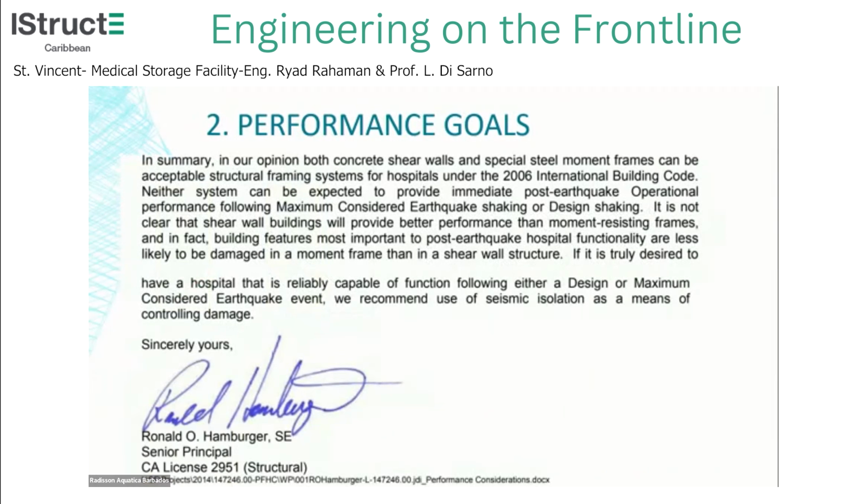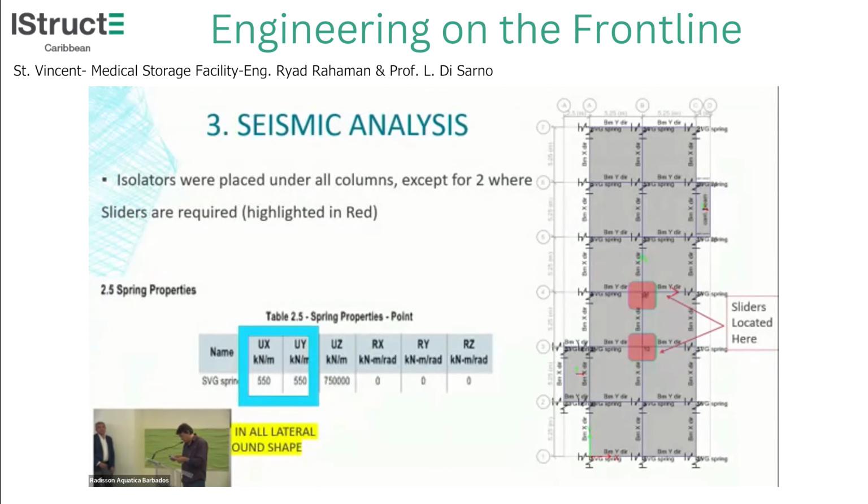But I got some consultation from the chairman of ASCE 7-16, the godfather of performance design. I thought he was going to tell me to go to performance design. What does he say? If it is truly desired to have a hospital that's reliably capable of following either a design or maximum considered earthquake event, we recommend the use of base isolation as a means of controlling damage. So it's not just Professor Luigi and I saying this. The godfather himself said it.